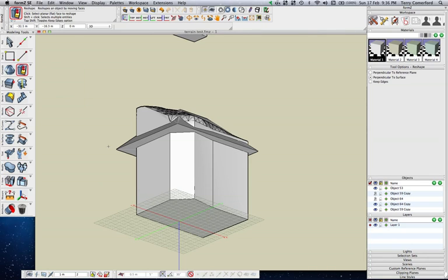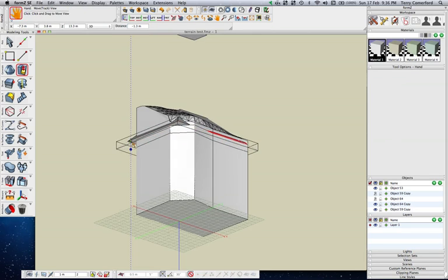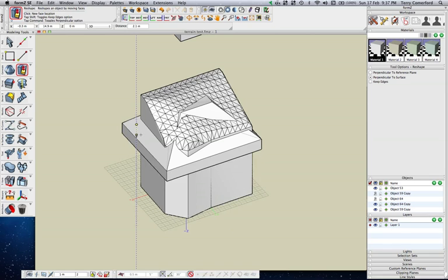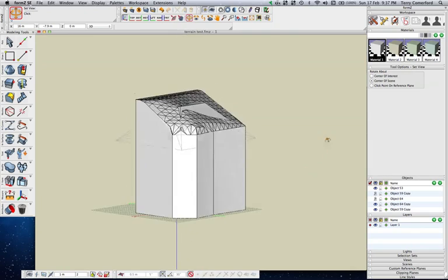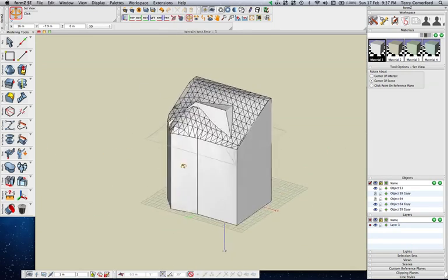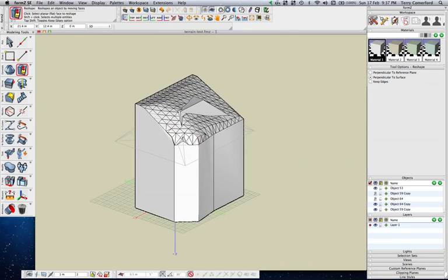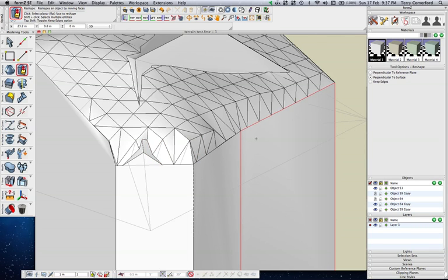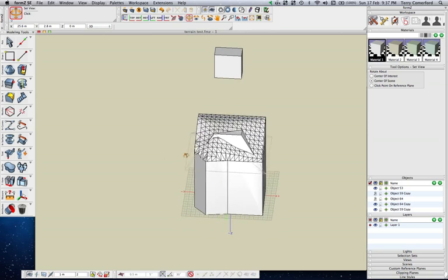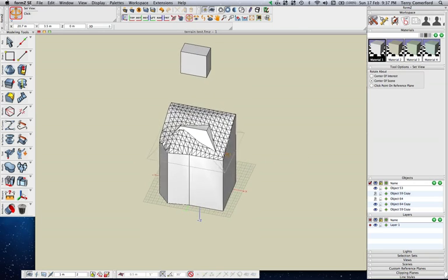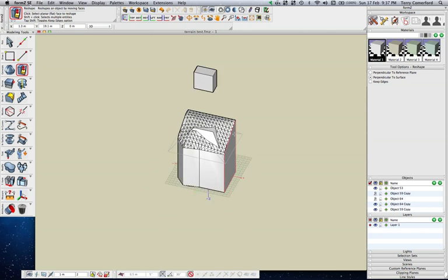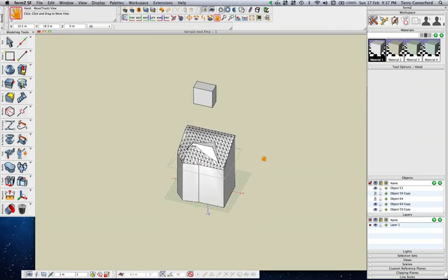If I just do a reshape this bottom edge here and reshape that upwards, you can see how I can start to get rid of the superfluous parts of the embankment. Just reshape that right up to there, and that's got rid of that embankment. I'm left with this one solid now. It's mucked up this little corner a little bit, but that's okay. I can live with that. I can maybe even edit that a little bit later. So I've got this surface here with this embankment. I'll get rid of these ghosted objects later when I'm finished. I'm almost finished this entire site now.